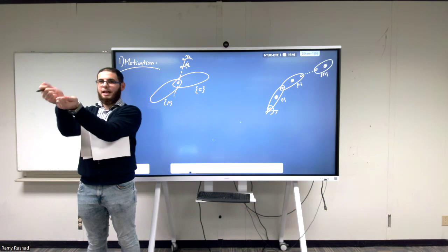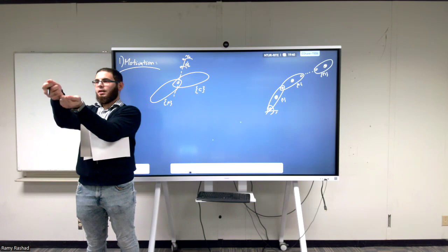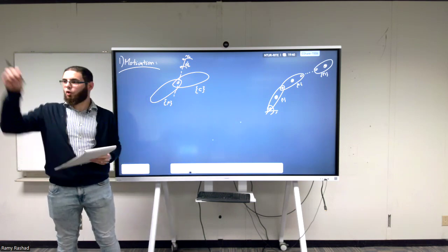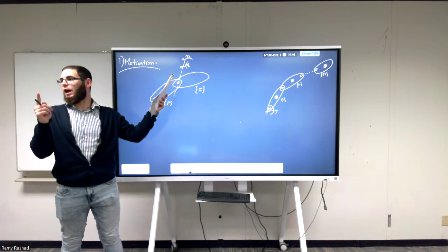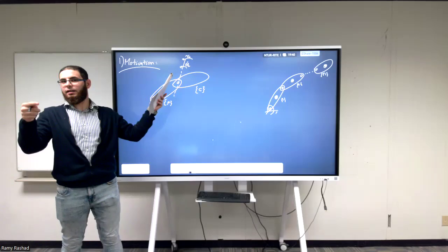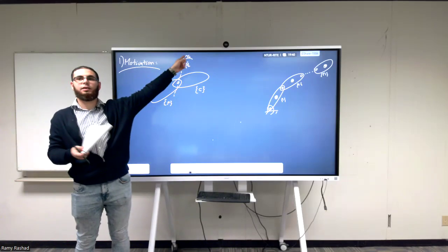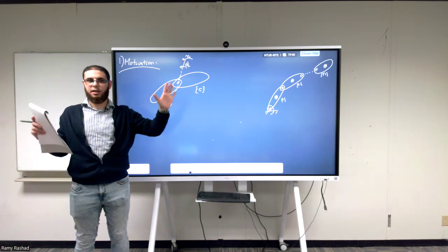No, so this is the motion that's allowed. It's not allowed to rotate like that. And there's a third, like this, right? So it constrains 5 of the degrees of freedom. So 5 of the components of the twist will be 0 between these two, and only one of them will have an angle that you can apply. If it's actuated, then this angle is actuated by some torque or something. Okay, so you all visualize the picture. Is that clear for everyone?